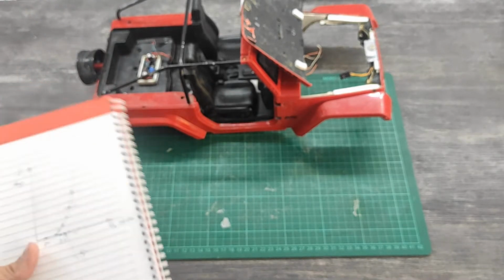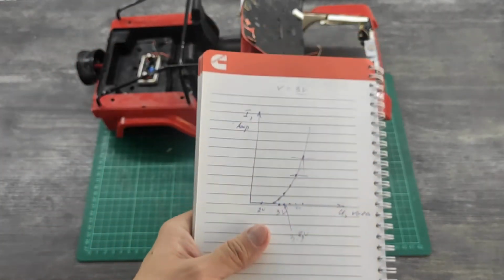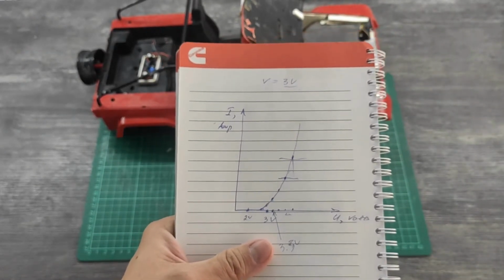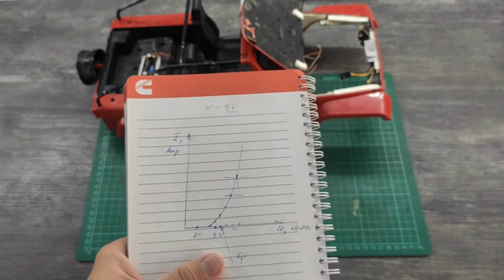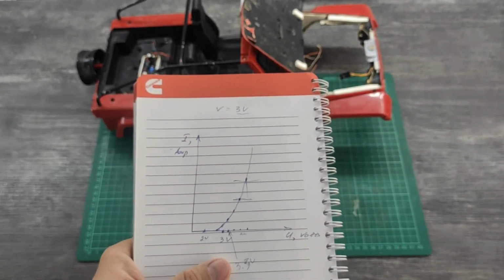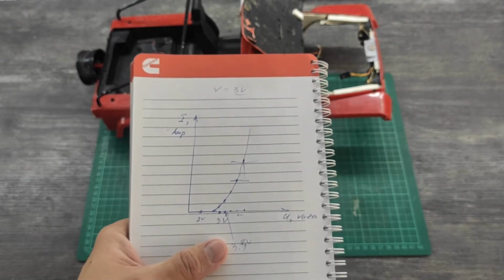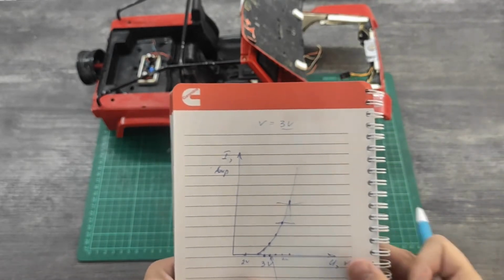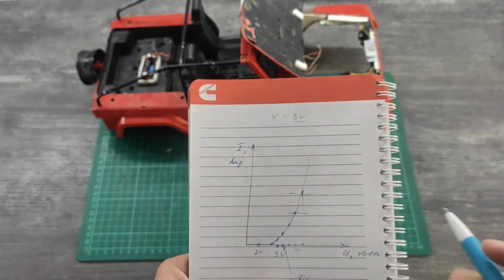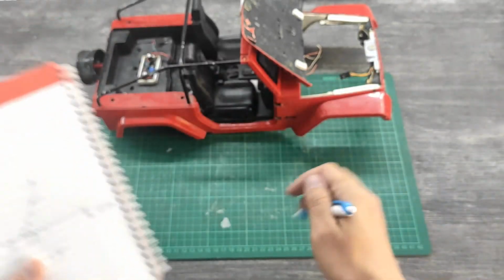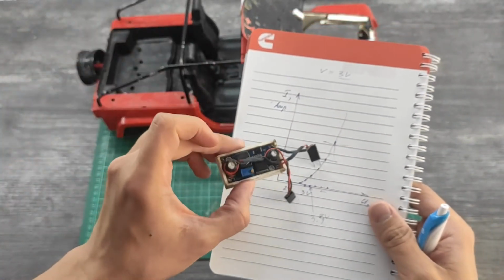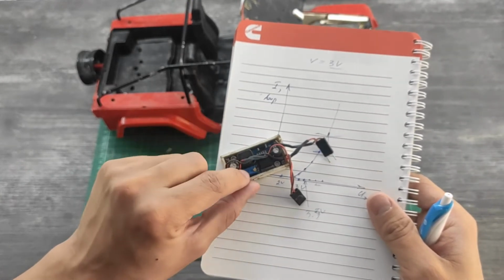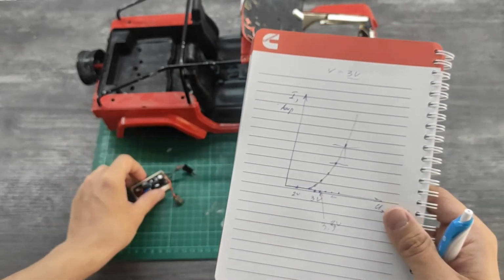But what I came across, going back to our explanation of how an LED acts: I just took two LEDs, connected them in series, and connected an ampere meter and a voltmeter to the circuit, and started to do the following. I took this LM as a power source for those LEDs and started to increase the voltage.